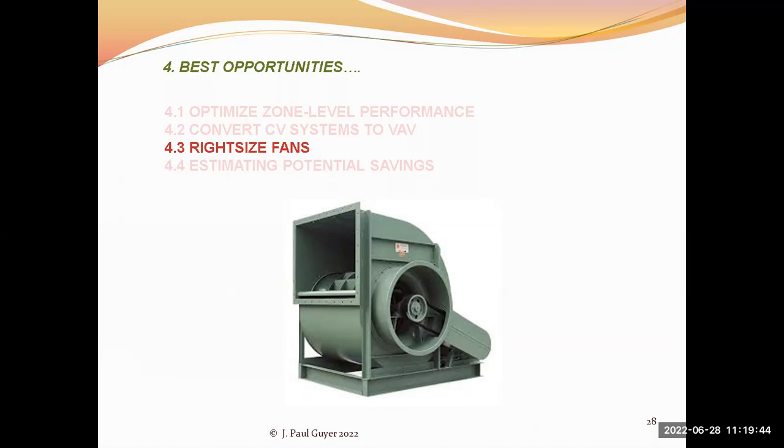And this change will significantly reduce the fan power requirements, reducing the static pressure. It's important to survey the occupants of the different spaces periodically to assess the comfort level. Are they comfortable with their air conditioning in their zone, or are they complaining? And so this will be a consideration.